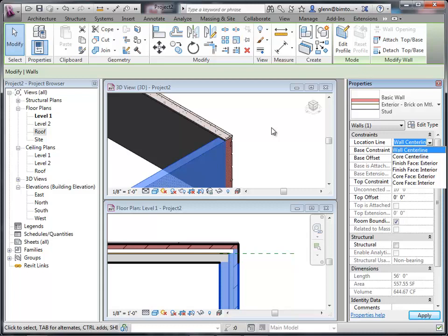In a lot of walls, you have some sort of central core, the main structural layer. And then on the inside and on the outside of that core, we'll have different materials. We may have some gypsum wallboard on the inside. On the outside, we may have some plywood sheathing, which gives it a substrate. And beyond that, we might even have an airspace and some exterior finish layer out here.